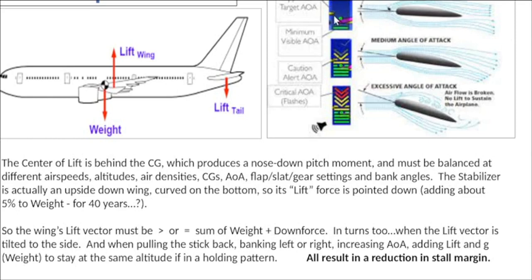This over here is an angle of attack indicator. In this case, everybody's happy. As we go down, now the nose of the airplane has been, the pitch angle has been increased. So the angle of attack is increased too. And that means this, actually the chord line through the wing here is what that line is. Down here, we have raised the nose too far, and we've messed up the airflow across the top of the wing. So now we're at or above the critical angle of attack, and this thing is flashing and making a sound for you, trying to help you out.